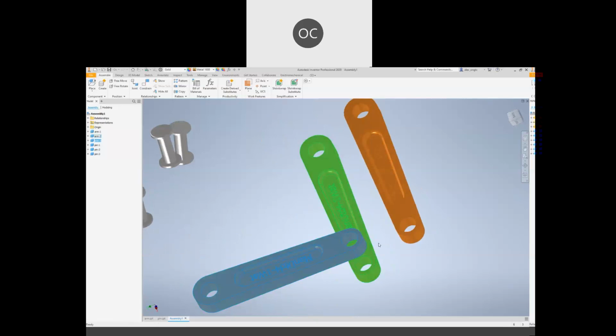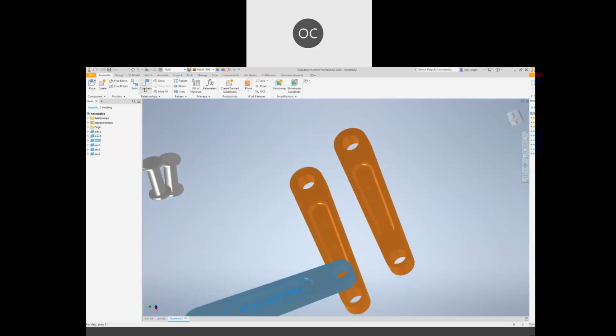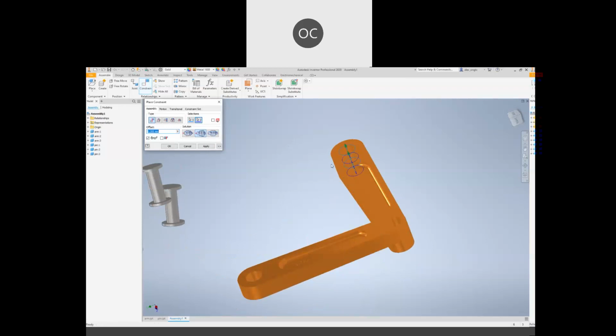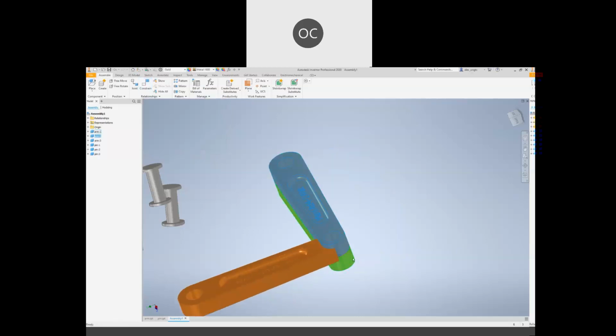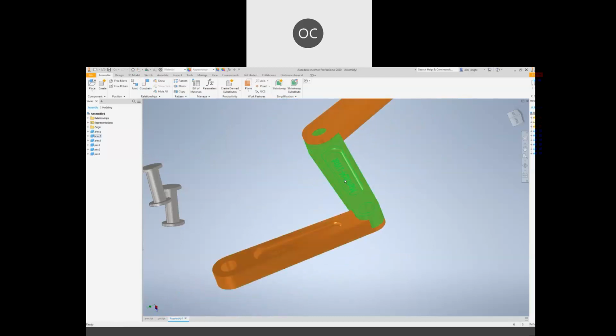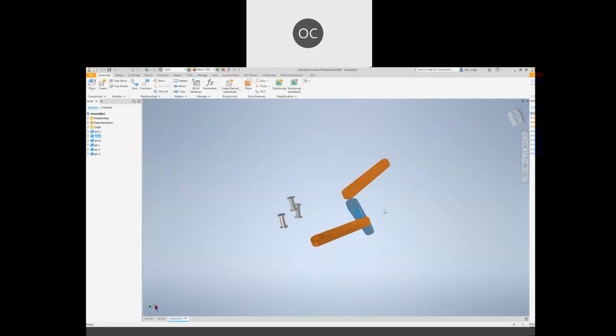Second, I'll show to you again, same method also. So this will be the larger circle here. So mate also, holes. And I would like to align with this hole. This will be the bigger circle, right? So you see that you will join up to that circle, center point, apply, then I cancel it, so that I can have a look at the effects. So you can drag now. So first thing will be mate center point. Please try on that.